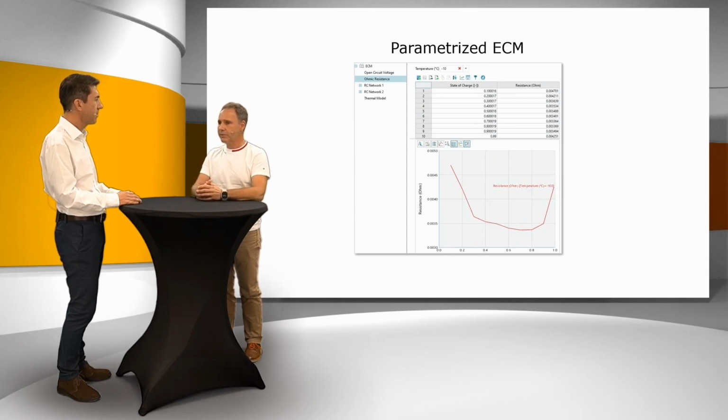On the other side, of course, when you're working on designing a battery cell, playing around with parameters like the anode layer and cathode layer thickness, you would like to see immediate first feedback on what, for example, the capacity change is. So now we have a dedicated KPI section. Whenever you make design changes to these battery-specific parameters, you immediately get information about how that is changing the characteristics.